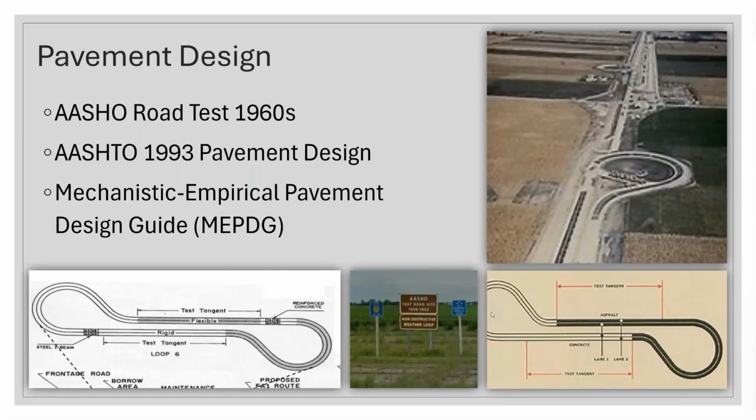Now, pavement design has been something that we've done for years and years. The biggest founding study that was done was the AASHO Road Test back in the 1960s, and that was up in Illinois. That was the original study, and then things developed over time. And then 1993 was the AASHTO pavement design procedure that most local agencies, I would say, use up until more recent times.